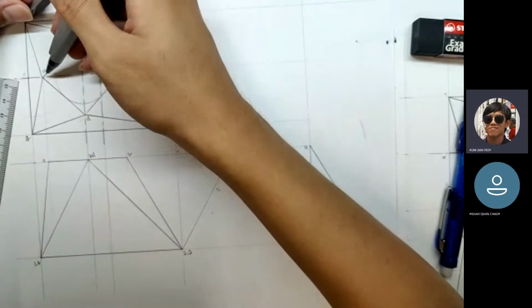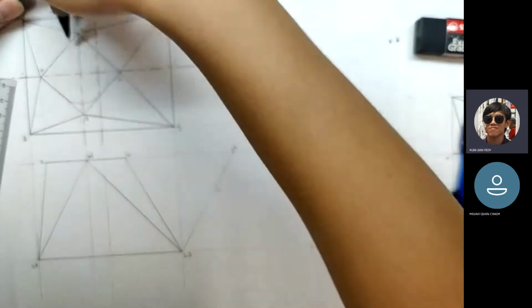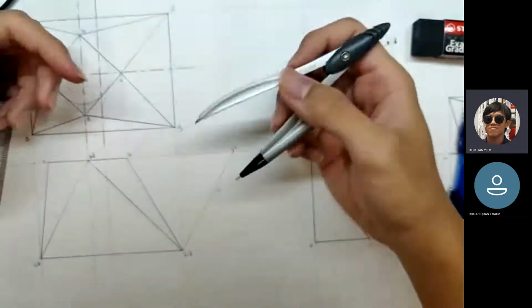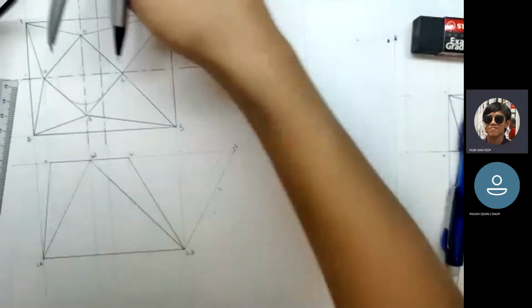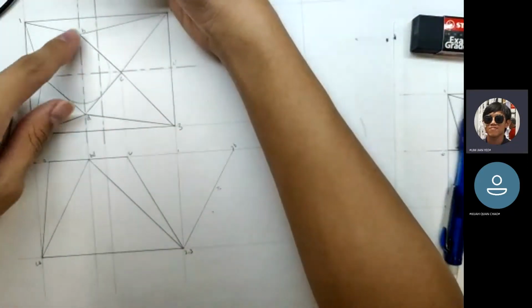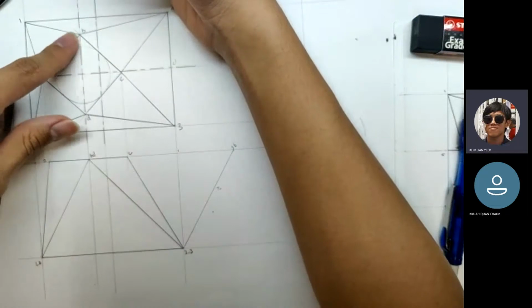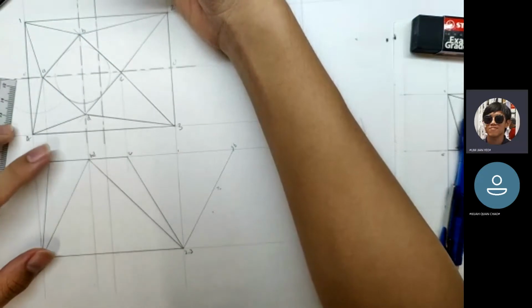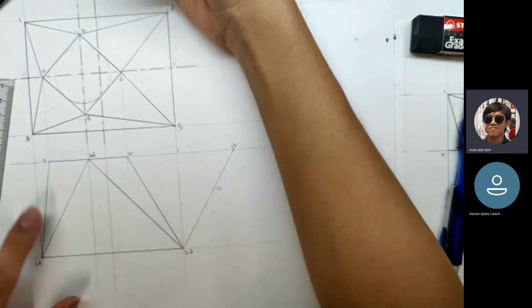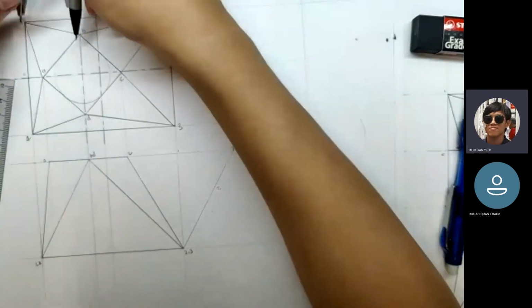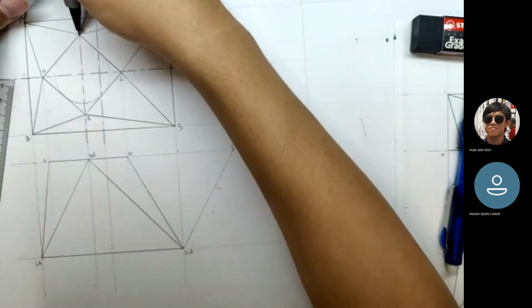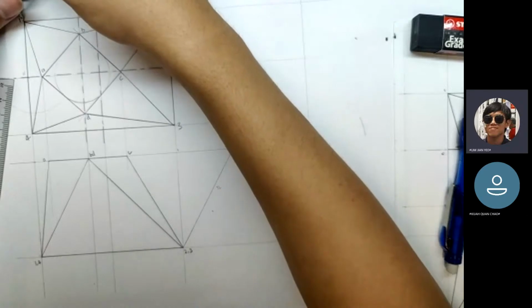You can measure here also. You'll find out that they're all the same. Some things you can find out after you draw it. Yeah. So why can I do this? Okay. 1 to B is not true length, right? But the height of this is true. So you take this, then you project it up flat.